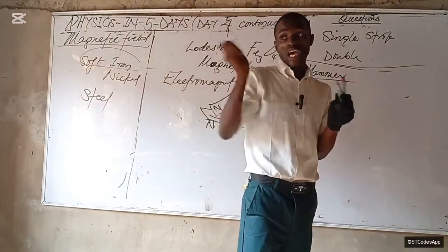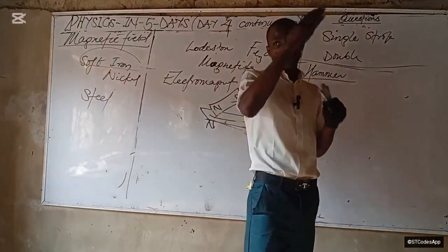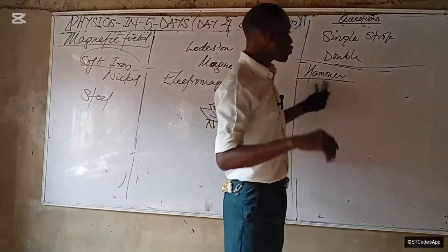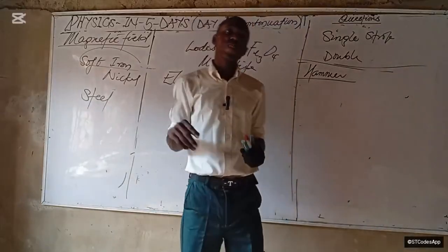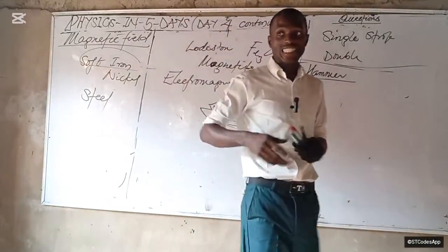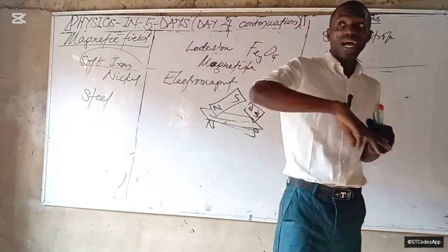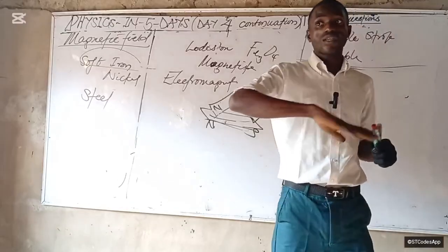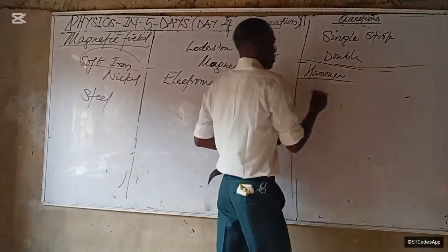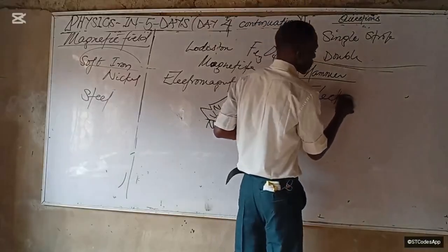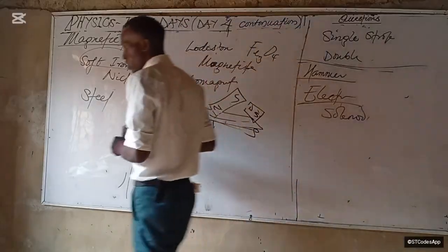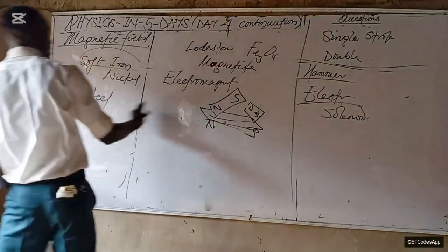What if you now wanted to stroke with two magnets? If you stroke with two magnets, the two poles that are stroking must not be the same, else you would get what is known as consequent poles. If you want to do double stroking, you will stroke with different edges. So if you are stroking on one side with north, you will stroke on the opposite end with south.